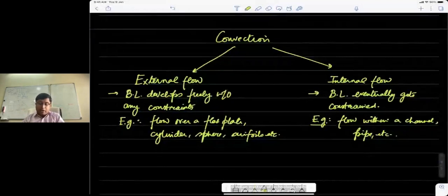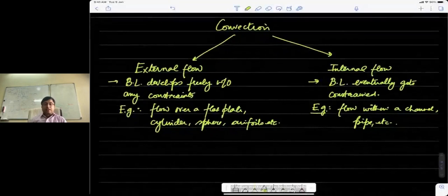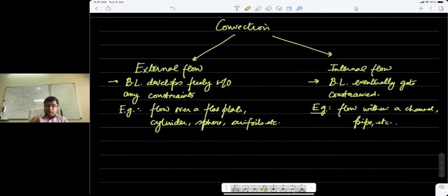So the primary reason why we are doing this analysis in this form is to be able to determine convection coefficients for different geometries. Now, as I said, geometry has a major role, even though the equations do not show that. But you know that dp star dx star comes from the geometry. So the geometry will actually influence what the convection coefficient would be for that given scenario.